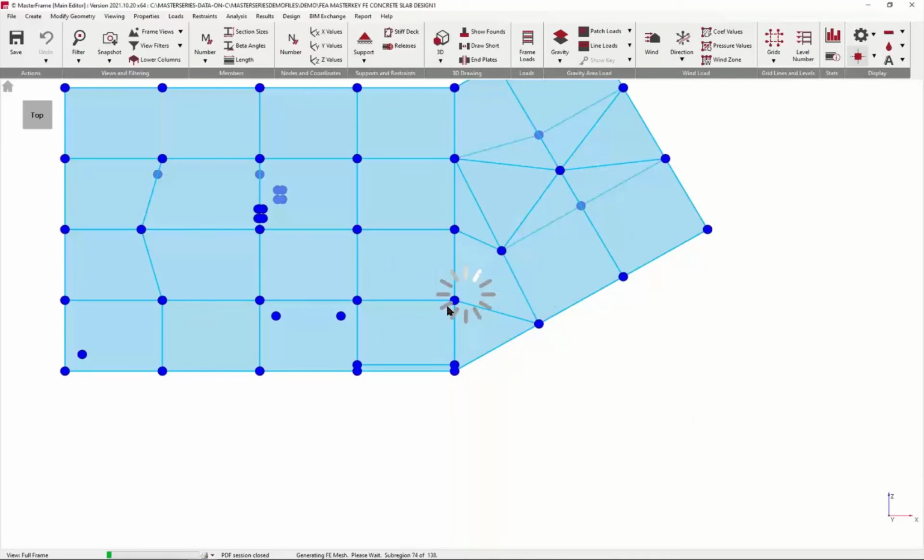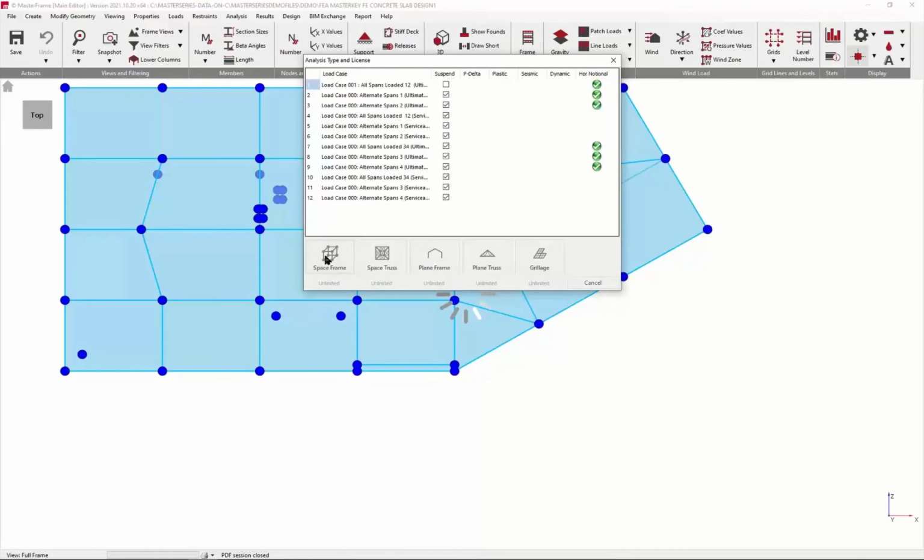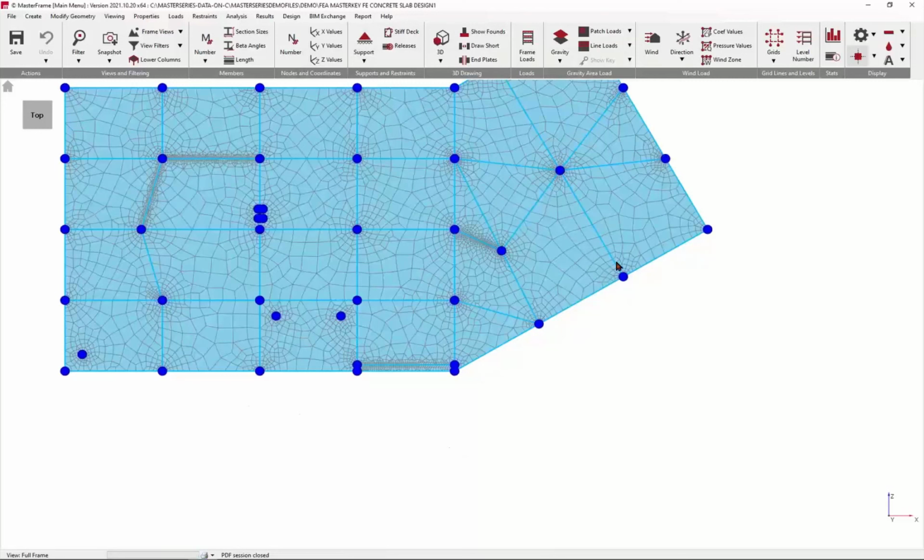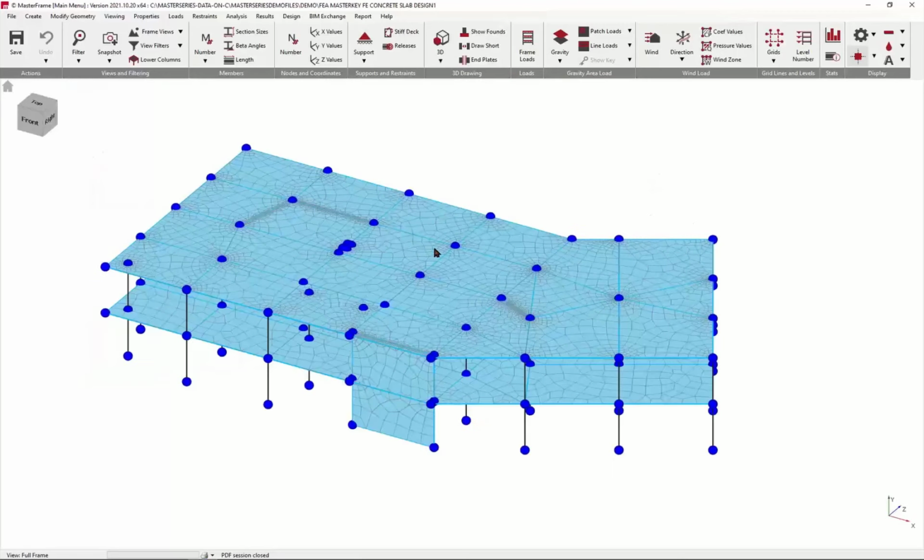Now the fingers need to be crossed when you do this, to be honest, because you need to be careful that you get a mesh that works properly. So it's not something I recommend with every single surface, every single structure. So there we go. And you can see now, because I asked it to mesh to internal members, I've got one element here and one element there. And that does give you a more accurate analysis in some respects. Not necessary, but certainly the other meshing to internal columns and walls can be very useful for reducing your errors right down.